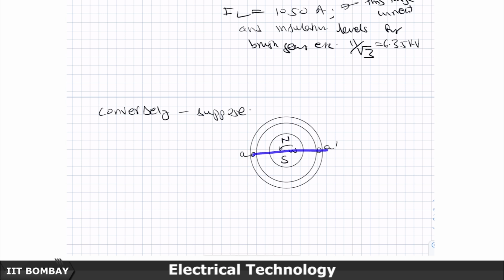So, if you put the B here, 120 degrees apart, and the opposite 180 degree side will be the B dash conductor, then this will create the B phase voltage to lag the A phase voltage by 120 degrees, and then this would be 60 degrees.